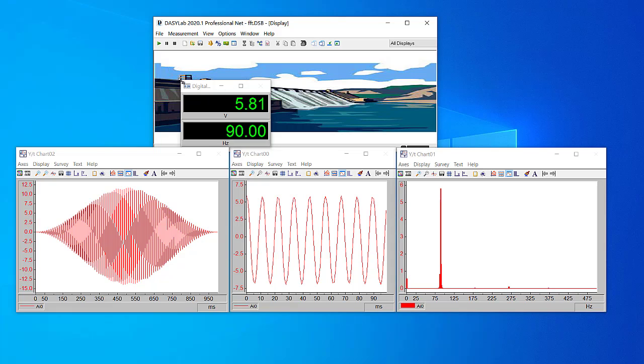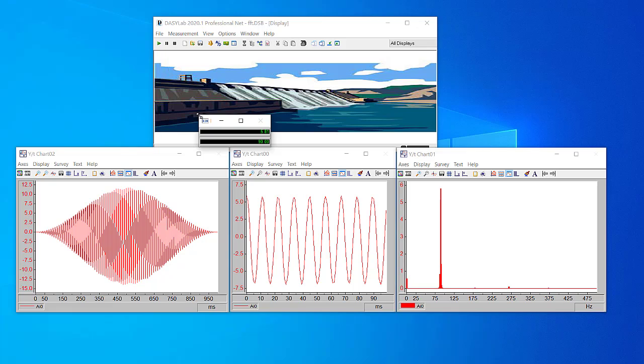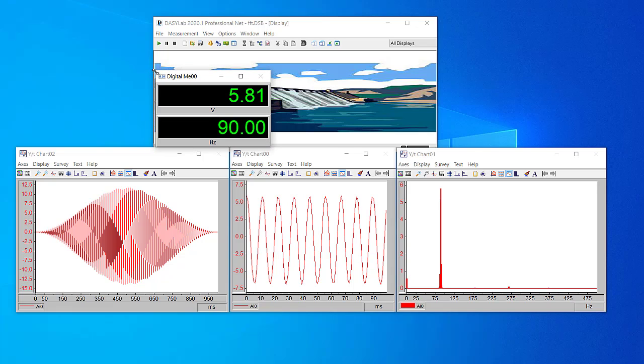You're limited with how small things can get. When you get small, you're taking up half the space of the window with window dressing. So with the Windows title bar and the Windows frame. We created the layout view to give you a way to control how your display looks in a fixed format that you design. So you're going to create, in effect, an operator panel or an HMI that your end user or you will be able to use as the operator panel, the display panel, or even as a report. So that will be the next thing to talk about.